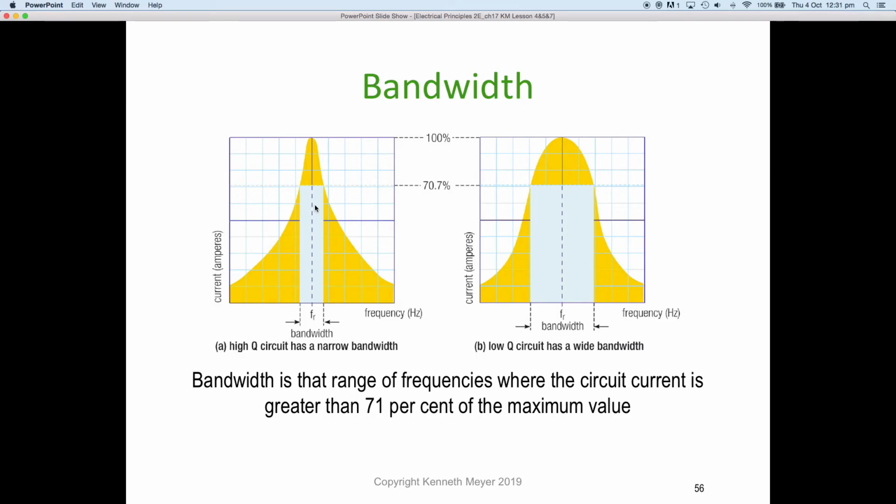So in radio circuits, that's what they're looking for. They're always looking for this one here. Try and get the Q as narrow as possible. So when you tune to a particular radio station or frequency, that's what you're letting through. You're letting through only the frequencies that sit inside the Q. And we can also use this in electrical substation systems, which we'll look at in a moment.